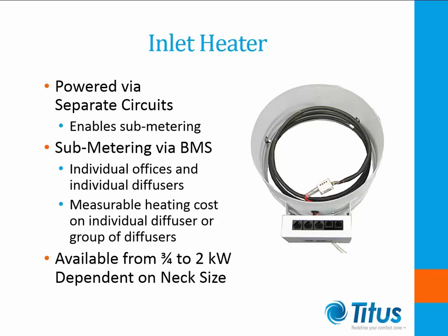These heaters are used for reheating conditioned air when needed to improve occupant comfort. These heaters are intended for trimming room temperatures or to provide limited heating in low-flow applications. If building primary heat is needed, additional heat sources would probably be needed and supplied by a central air handling unit.